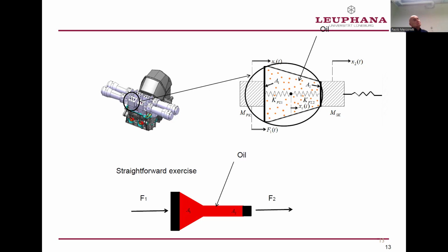The reason is the exhaust valve is more difficult to control, because in the opening phase we have to work against the pressure inside the cylinder. It is extremely difficult to guarantee that the exhaust valve does not crash against the cylinder. Last time I told you a little bit about that. The project was basically finalized to replace just the intake valve from the cam.